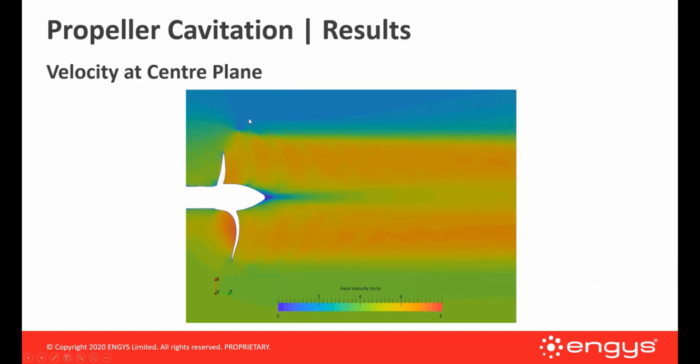You basically model the propeller in open water condition, but considering the effect of a propeller mounted behind the hull. So you operate in non-uniform inlet conditions here, and this is quite tricky. You can solve the problem using a steady state approach or an MRF transient approach, but also a fully transient dynamic mesh motion, which was used for this particular case,